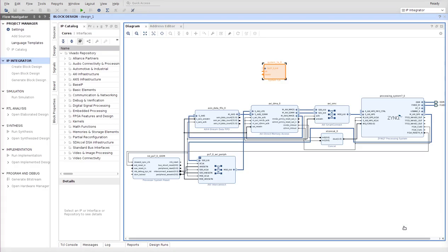So yeah, you just change that, and then you have two slots, and then let's say, because when it's AXI stream, there is no double channel, it's just single channel from master to slave always. So basically the master is always writing to the slave, and the slave is always receiving data from the master. That's why it's unidirectional.